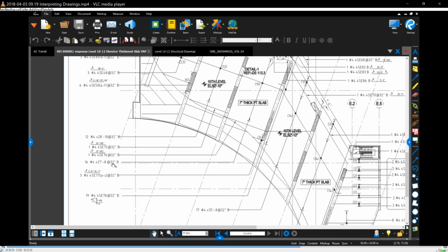Right, shop drawings. The drawings we saw previously were from my old design firm, and those were the contract documents, what we call contract documents. These would be equivalent to our FRP shop drawings, but these are for rebar. So another company interprets what the EOR wanted on his or her project, and then the rebar subcontractor provides rebar shop drawings that then, just like ours, go back to the EOR to review to make sure they interpreted them correctly. So they go through the same process we do.